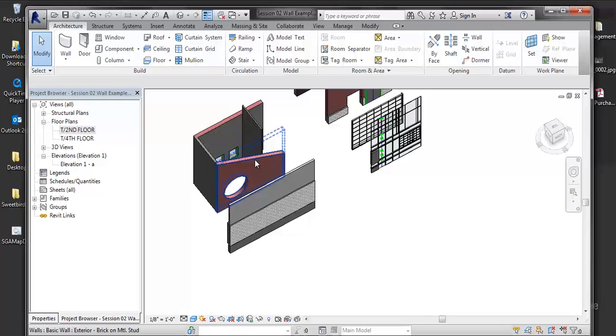Or you have physically stacked walls with a lower wall and an upper wall, and then divided by a reference plane. And you're editing the profile, the top and bottom of the walls, to control where that change occurs. So I think it would definitely depend on the specifics of how you go about modeling; what the best way to model that would be is a different answer.